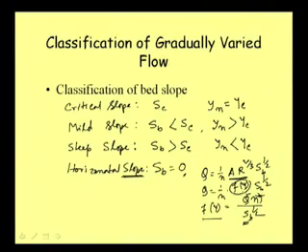And on the left hand side of this part, other than the sectional dimensions like b, and side slope z if it is a trapezoidal one, we have n and other things remaining fixed. Suppose yn will remain on the left hand side. So, ultimately, if this left hand side is to become equal to infinity, yn will have to become infinity.